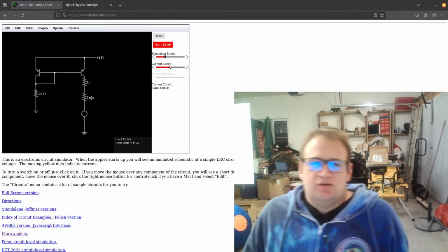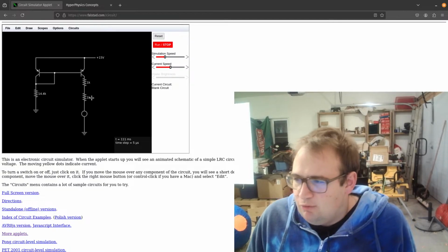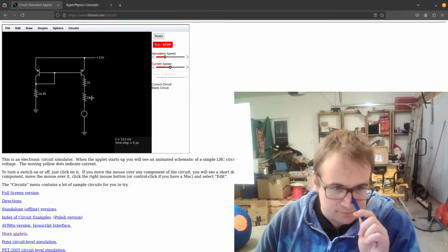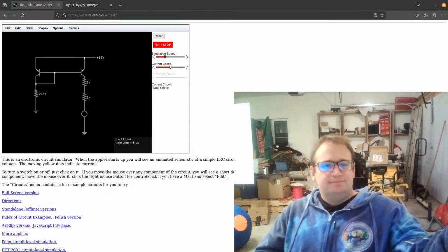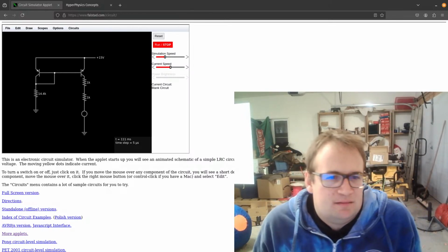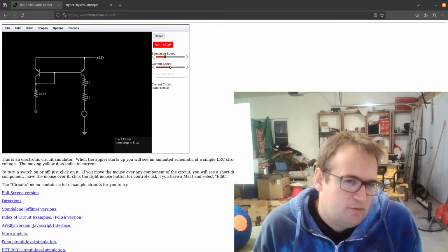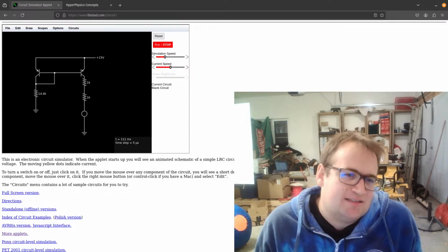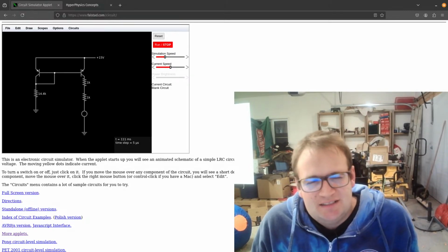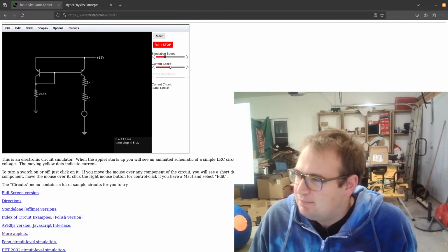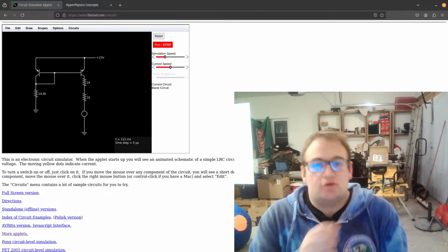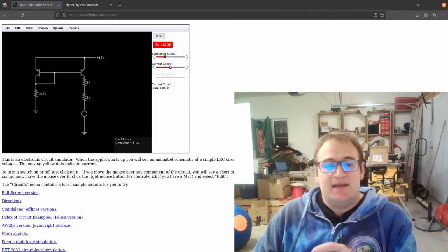There we go. So basically, how I think this will go is that the left side PNP transistor will get minus 15 volts. Oh, okay. No, I see why they did 14.4K. That makes our favorite current, which is 1 milliamp. And then that 1 milliamp is going to get drawn out of both of these bases.